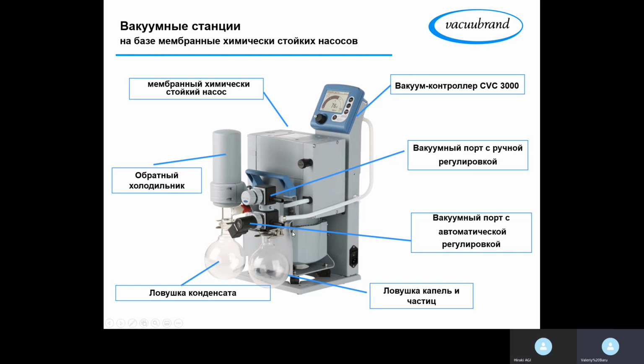So once some solid particles get into the vacuum line, into the tube, the solid particles will just drop onto the bottom of the flask, and will not go into the vacuum pump. It is important to have such a protector. Why?